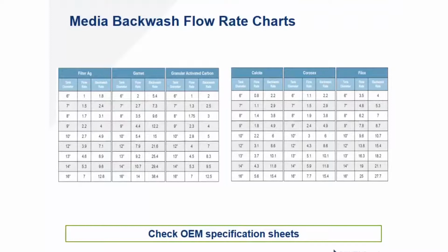It's not as thick. If you want to think about it this way, just a kind of crude analogy, say you had a plunger. Cold water is a plunger with no holes in it. Warm water is a plunger with holes in it. So as you push up, water is going to go through and not have as much force, whereas the solid plunger is going to push everything up uniformly. So the reason you have a longer time with warm water is so you adequately lift that bed.